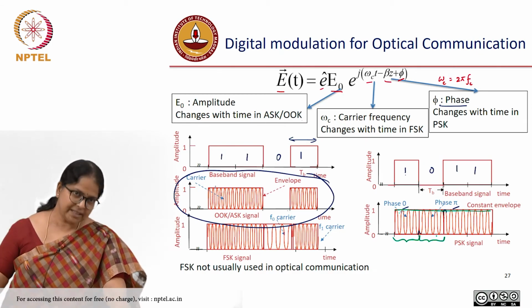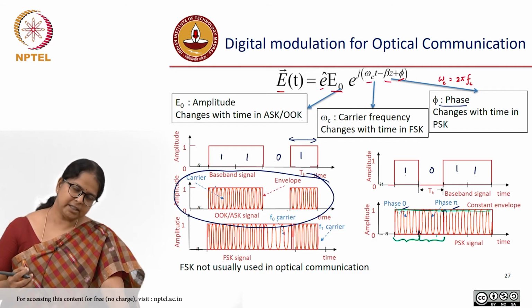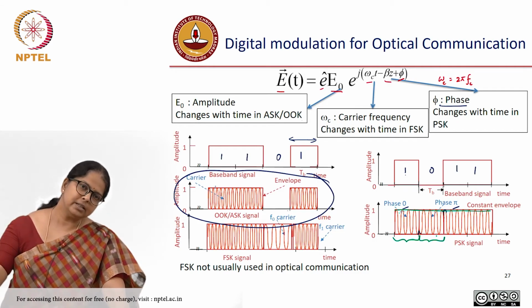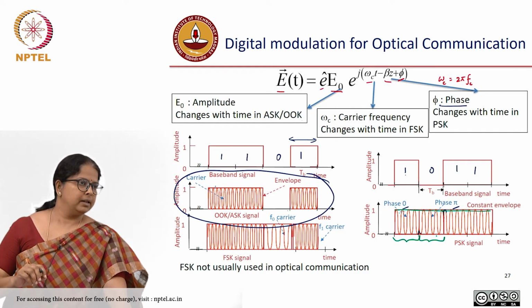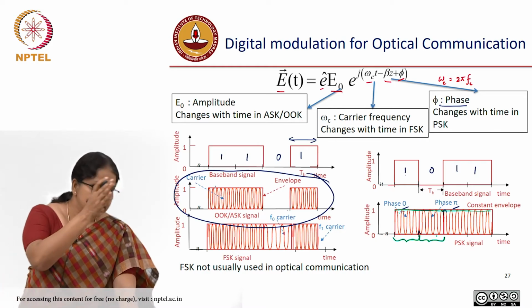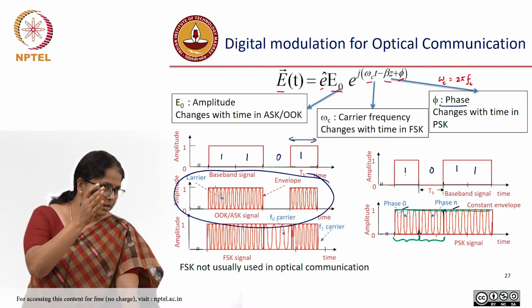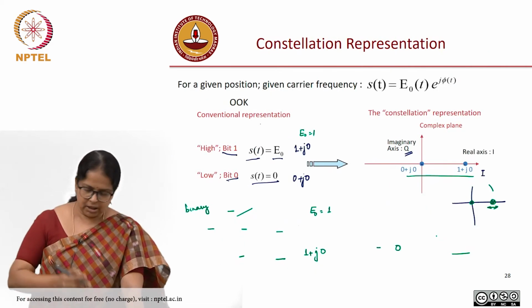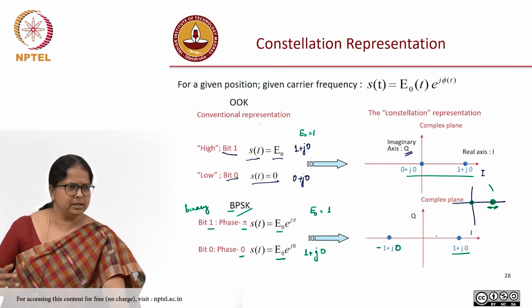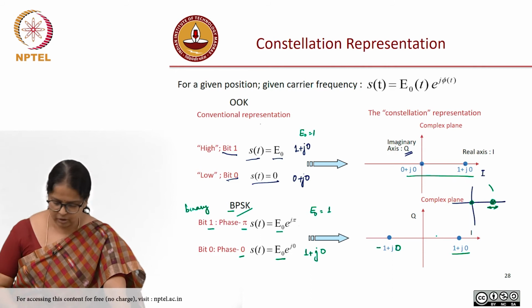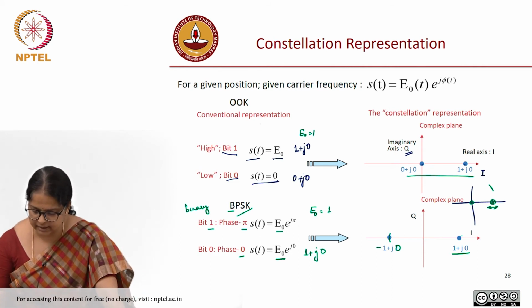So, you need to have a phase detector, and the phase detector is going to tell you whether you received a 0 phase or a pi phase, and there could be an error in phase depending on the noise in the channel. The noise could be in transmitter, receiver, channel, etc. So, that error in phase will come out as this angle.